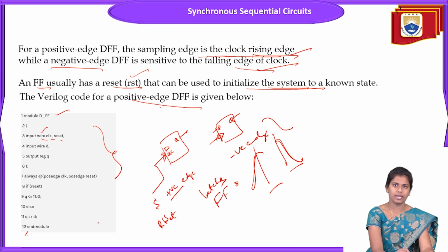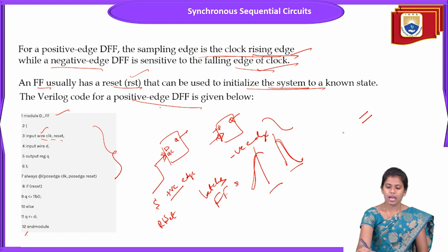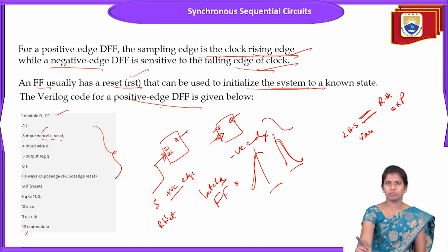So here, wire is nothing but a net, and a net is a variable. In the assignments, we have discussed nets and variables. So under net, what sort of nets do we have? Basically, net is nothing but a variable. In the assignment operator, usually we represent it with equals to, and on the left hand side we see all the variables, and on the right hand side, we see the expressions. The variables could be in vector as well as scalar form.